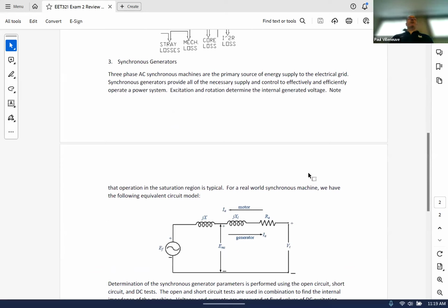And that was a rotor that had windings on it, and you only had a set of windings that would provide DC energy. You need to have DC energy, and the reason why is because you need to make sure that the power going in always produces a constant north and south. It doesn't change. It's not rotating on there. It's not inducing a magnetic field. It has to be a fixed north and south. And that is what causes it to be a synchronous machine, because it always is north and south. It never changes its magnitude or its speed. It's fixed at that value.